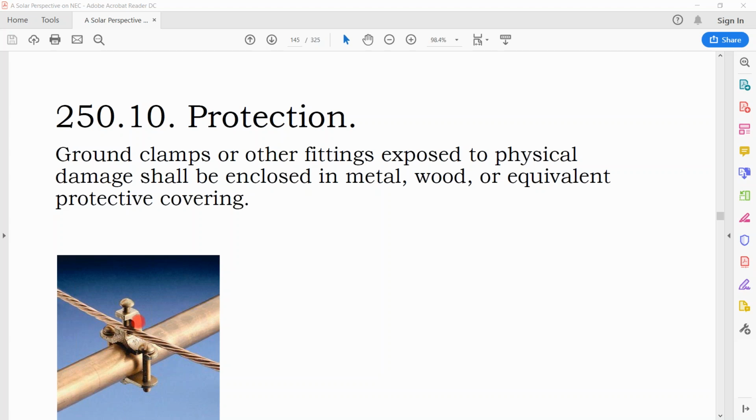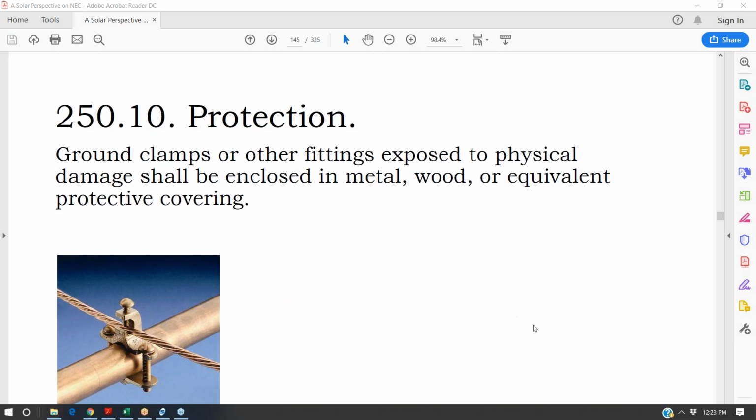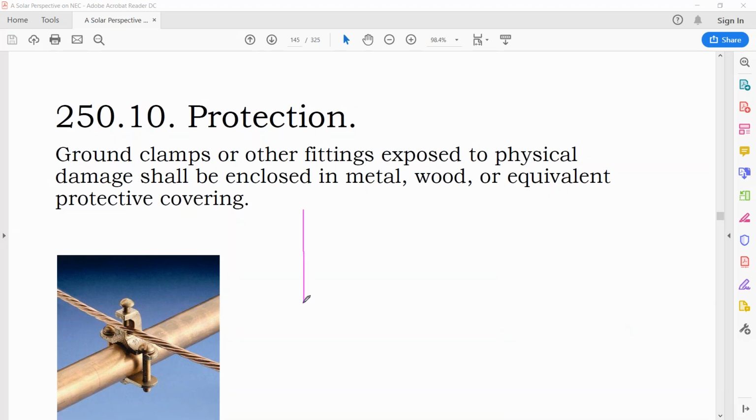Another thing that's weird about Mississippi is you can drive a ground rod 8 feet into the ground without any equipment. It's a weird technique, but you basically take your ground rod, which is 8 feet long, and poke a little hole in the ground and shove your ground rod into it, and then you take it back out and pour water down the hole, and you can keep driving that ground rod deeper and deeper by adding water into that hole. It's like mud, and it just sucks it right in.